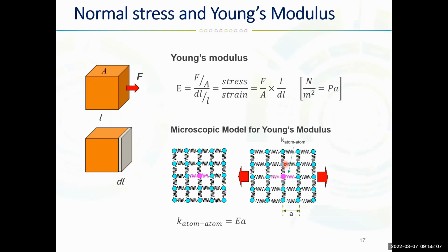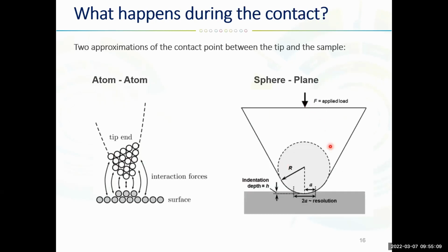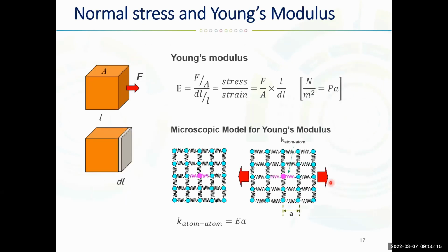Whether a rigid tip or sample, or a soft tip and sample are interacting, from here on we will stop thinking about the tip as an atom-atom interaction, and I will talk about the bulk approach. So here is Young's modulus, and the question is how contact force or contact energy increases as a function of tip displacement into the sample.